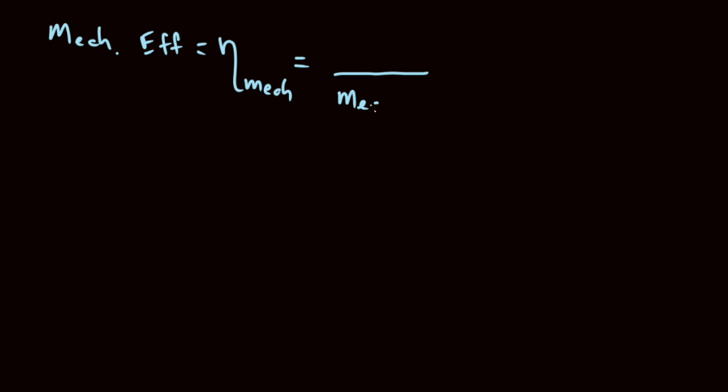In more practical terms, we are talking about mechanical systems. That was a situation where we were just looking at heat being transferred to heat up water. So in general, we're talking about mechanical systems. So for mechanical efficiency, this is equal to, we have the symbol eta, and we typically just write mech for mechanical efficiency, and that is basically the energy input. So it's the mechanical energy input at the bottom, and at the top we put the mechanical energy output.